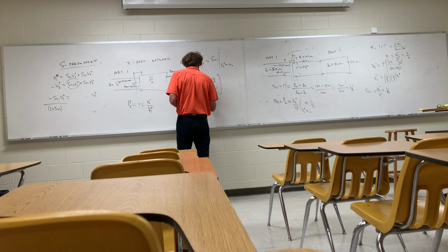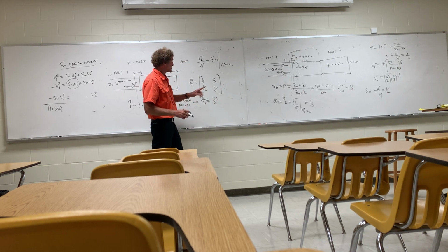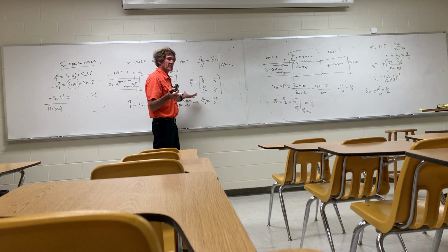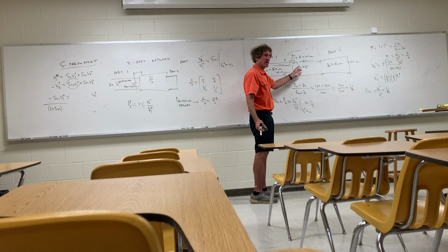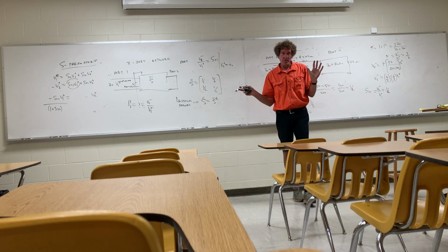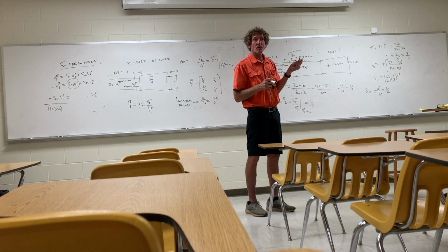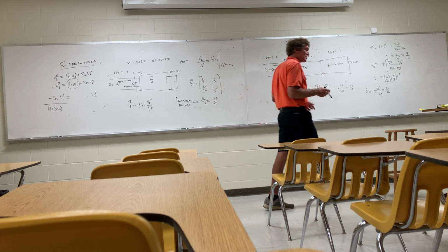That's where S itself, the matrix, is simply equal to S transpose. Y'all know what transpose is? You had linear algebra, right? You just shift these two parameters, flip them, and you get a transpose of the matrix. Well, to me, it's nice. Okay, we can call it reciprocal. I call it a symmetric network. This is a reciprocal network. You look at it one way, it looks identical as looking at it the other way. There's nothing different about it. So you can flip it around. You can take port 1, make it port 2, make it port 1. It'll have the exact same properties. That's effectively reciprocal, or I call it symmetric. And either one, this is a definition, I guess, used by the industry.